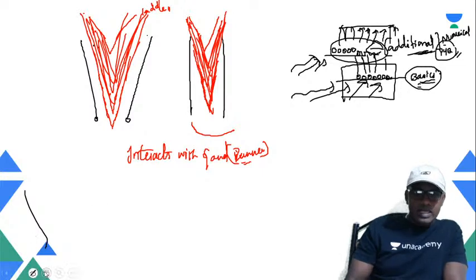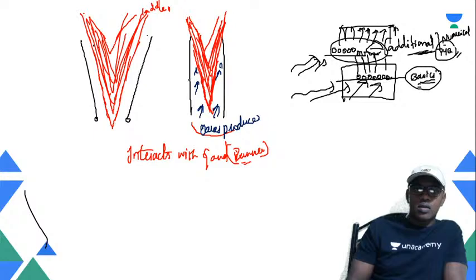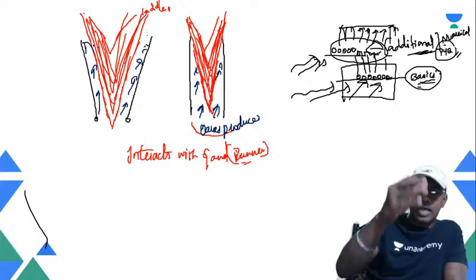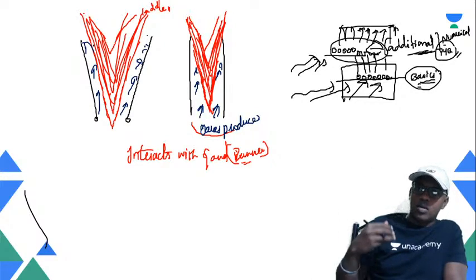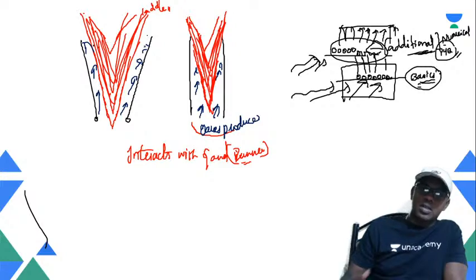and the gases that are produced cannot escape, but here they can. So this is what we call the aspiration effect. Otherwise, the gas remains within the cavity and it can form porosity, it can form bubbles inside it, and definitely the casting will be full of defects.